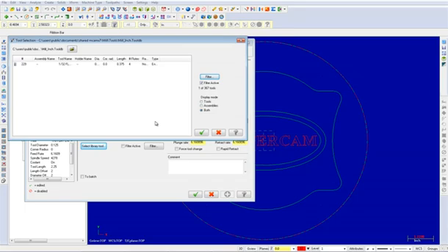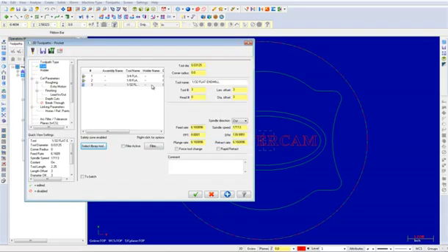In the tool selection dialog box, you should now only see a 1/32-inch flat end mill. Select this tool and then choose the OK button. Your tool will appear as shown. Input the following comment: remachine the pocket. Once complete, select the cut parameters.